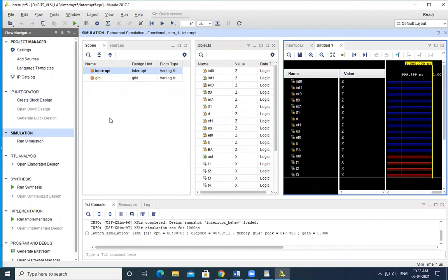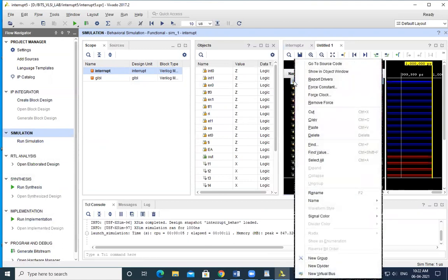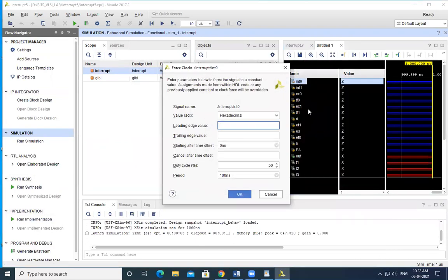So I think up to this step, everyone might be very familiar because you can do it in your Vivado. After that, RTL analysis, synthesis, implementation, program and debug all come for FPGA implementation. I'll tell it one by one. Before going to RTL analysis, let me input here. We have to check whether our program is working. I'm inputting values.